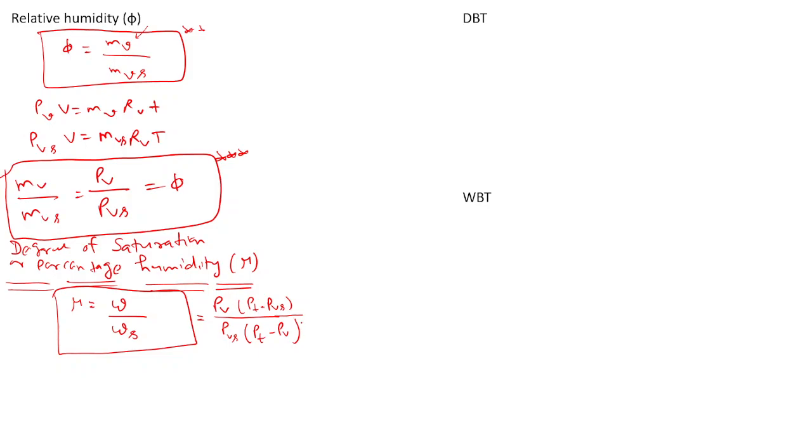Yes. So after that what will become? It will become phi, this first term. And PT is like in kilopascals. If you convert, this is usually 1 bar, 1.01 bar, our atmospheric condition. And this PV, anyone knows the approximate value of PV, PVS means water vapor pressure? It is generally 2 to 4 kilopascals.